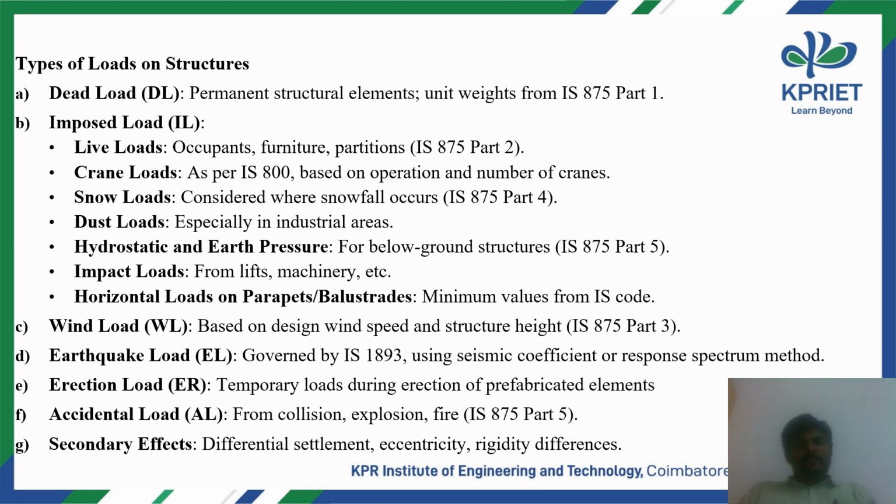So the next one is wind load. Because the structure is light in weight, you must consider wind load. Another one is based on the seismic zone map of India, you need to consider earthquake load also. The next one, erection load, is a temporary load during erection of prefabricated elements.